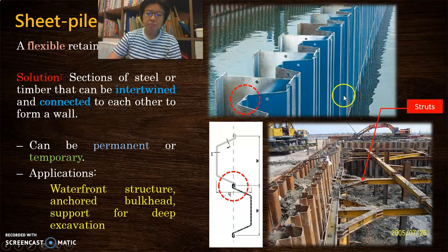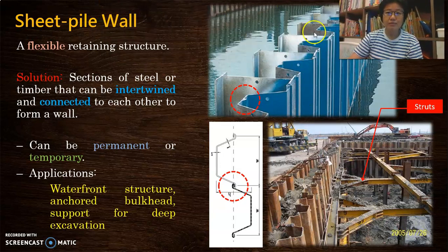And for deep excavation, normally we put in struts as well. We have these supporting struts cutting across the excavation site, and you have corner struts as well. Why? To make sure that the wall doesn't cave in. Alright, what did we say? It is flexible, hence you got to take care of it, alright, by putting in the struts.